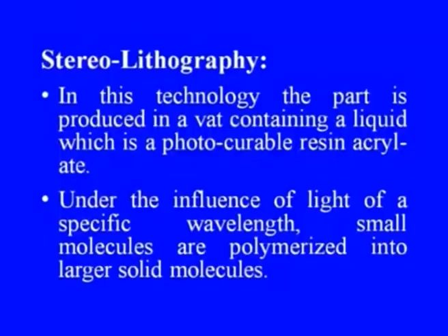Next, let us discuss another important technique in this series, which is stereolithography technique. In this technology, the part is produced in a vat containing a liquid which is a photocurable resin acrylate.